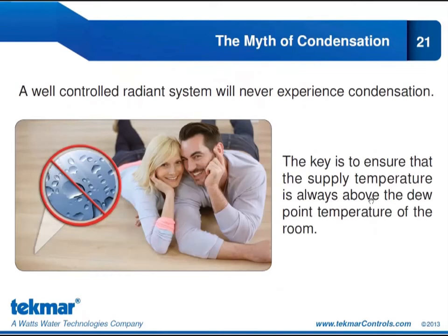Certainly the myth of condensation is something that we need to address right away whenever we start talking about radiant cooling. And the key to tell people is that if you have the proper design, the proper installation, and the proper control, you will not experience condensation. But it does rely on having the proper system design, the proper installations, and of course the proper control to make sure that we are monitoring that relative humidity, calculating the dew point, and making sure we are always above that dew point temperature.